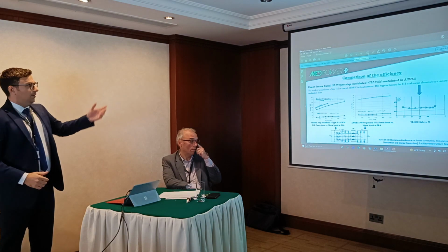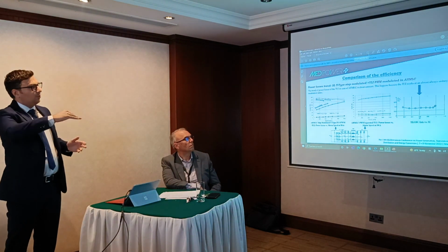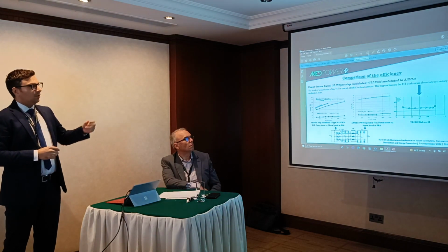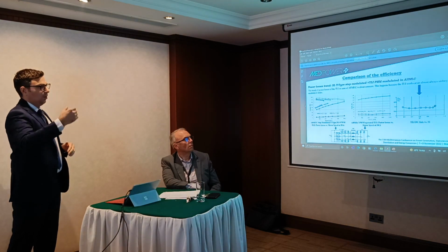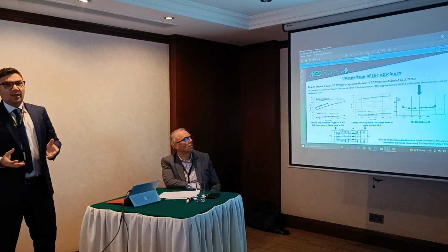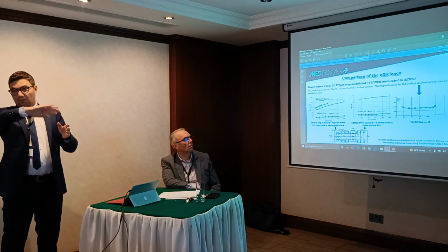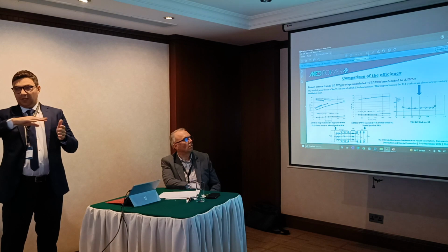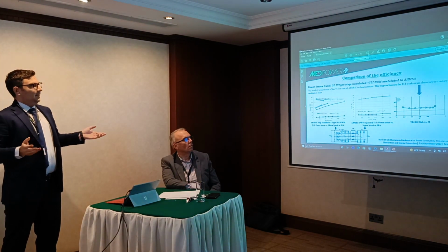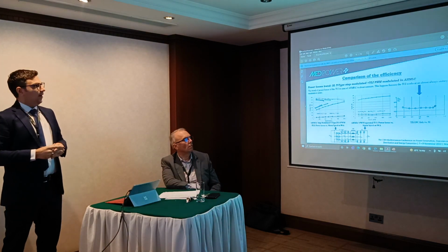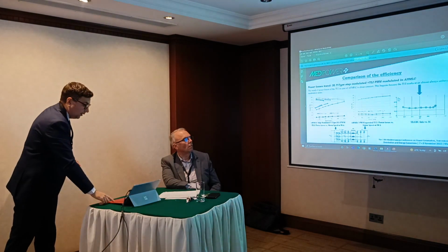About the 2-level, the trend of power losses of the 2-level converter is about constant because it works at almost unitary modulation index, as shown in the figure on the right. So since the trend in case of PWM depends on the modulation, the trend of the efficiency depends on the modulation index. The modulation index is almost constant. In this case, the 2-level converter doesn't involve problems about efficiency.